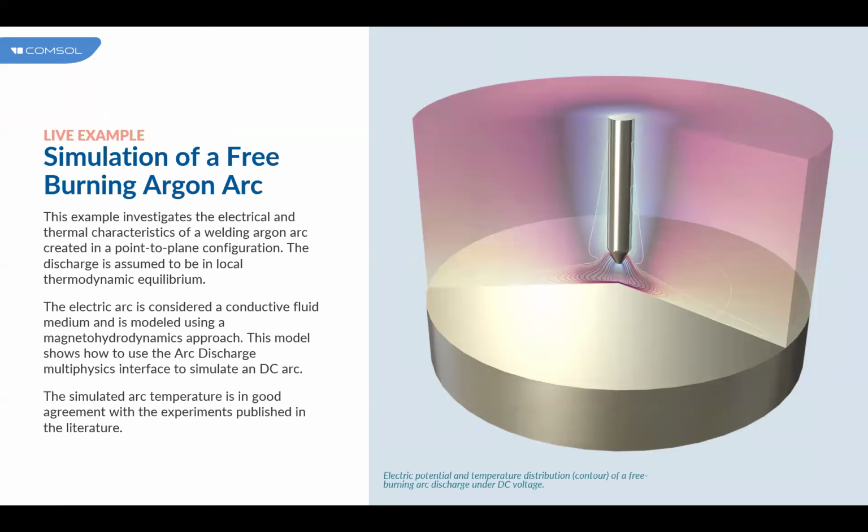Also, I would like to show you one more example, and I hope we have enough time for that. Electric arcs have nowadays a large range of industrial applications, including cutting, welding, spraying, waste destruction, and surface treatment. Arc discharges are assumed to be under partial to complete local thermodynamic equilibrium conditions.